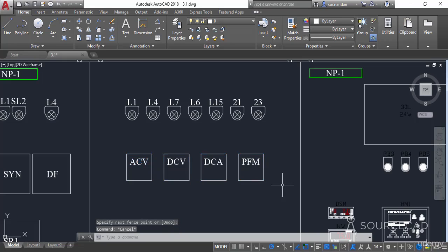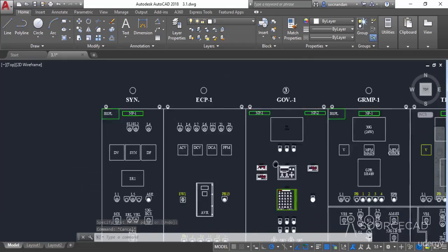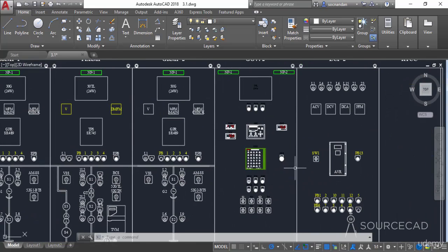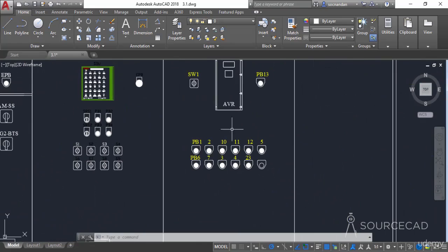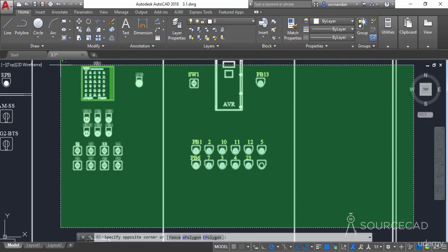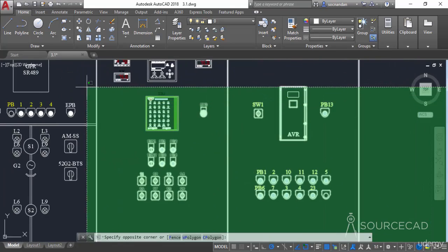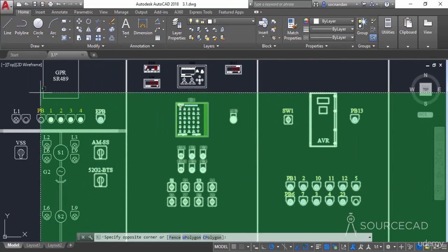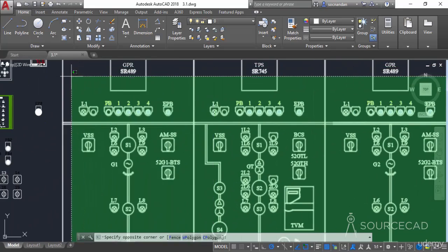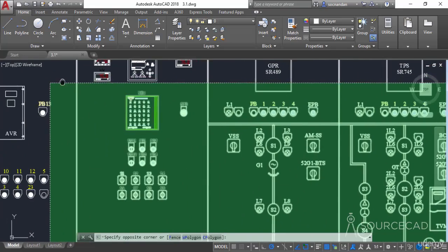In the AutoCAD 2018 version, AutoCAD added an off-screen selection, which is helpful for selecting this kind of long geometries. Let's say that we want to make a selection by zooming in on this drawing, and we just want to start our selection somewhere from here. Now we are including the objects in our selection set, and along with inclusion of objects, we are also moving the drawing towards the right. We are panning it here, and now we are including many objects.